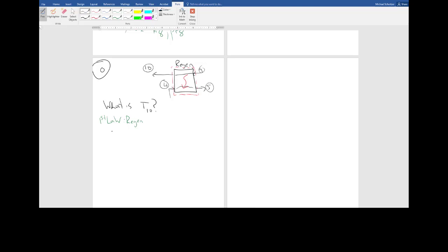Right? So here, now we can say dE by dt is equal to Q dot minus W dot plus the sum of m dot in, h in plus V in squared over 2 plus gz in, minus the sum m dot out, h out plus V out squared over 2 plus gz out.